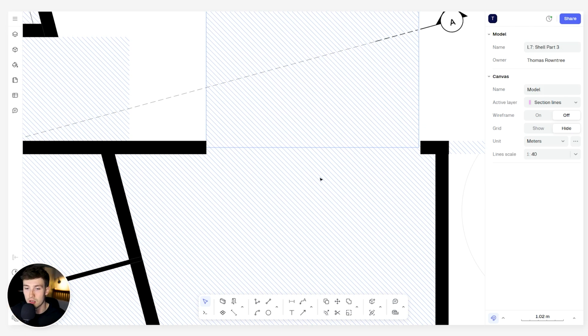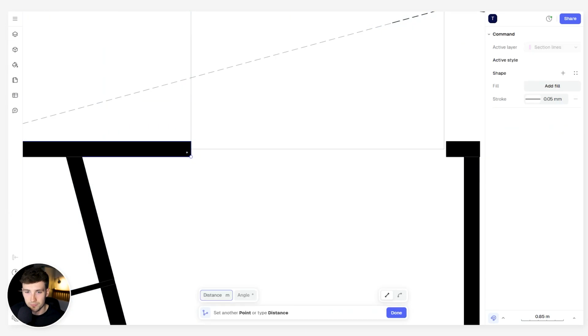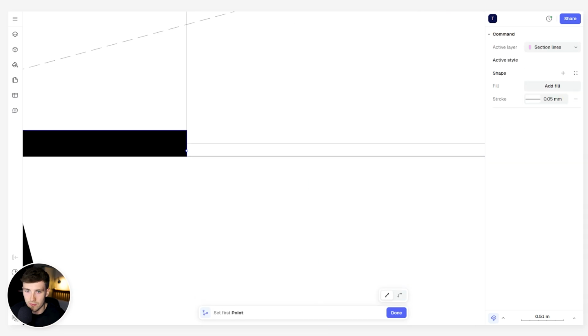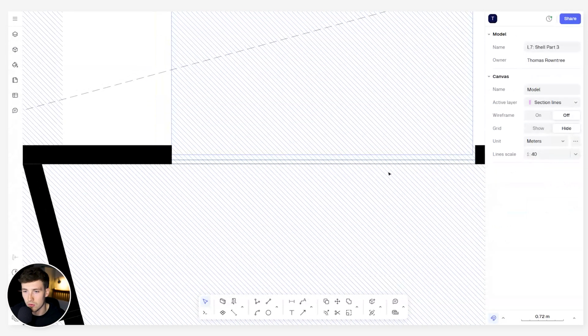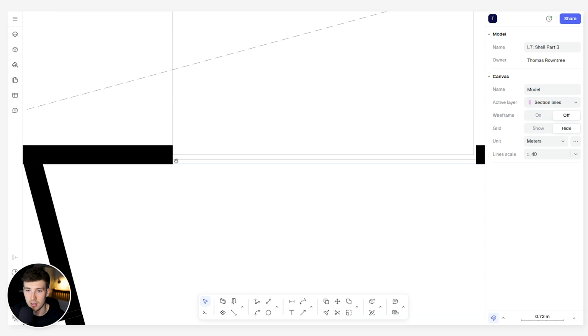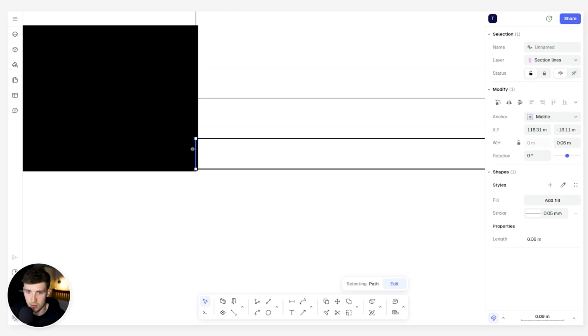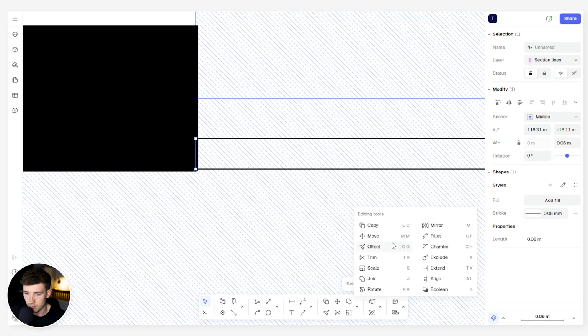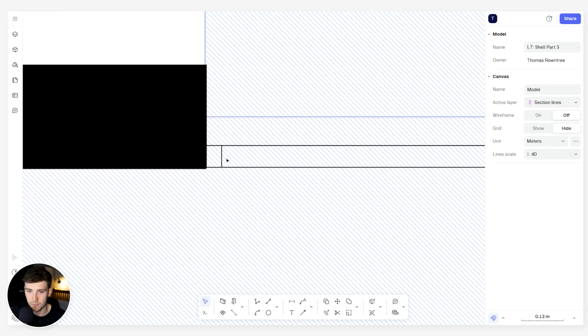Additionally, if you couldn't find a block that you wanted to implement into the drawing and you wanted to create your own, you can do so. So one thing that I'm going to draw here is for this garage door, we could very simply use the polyline and create some kind of indication of a potential, I don't know, shutter or kind of door that's going to come down and land into place. We can add a bit more detail to it to show that there's going to be some kind of edge to it. We can then offset that edge by heading down into here and offset that by, I don't know, let's say a 50 mil edge.